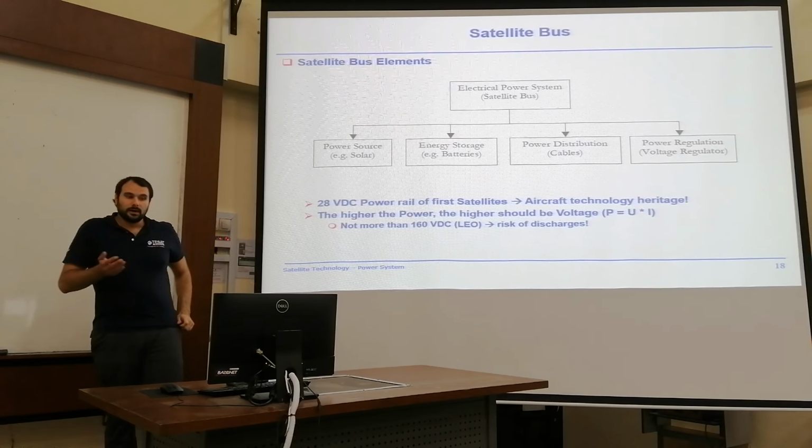We have a very simple system. We have the satellite bus that you can power by either the solar array or the battery. But in terms of the battery, we need to take care if we have a charge and discharge unit, and in case we need to dump some of our power because our battery is full, none of our components want any more power, but the sun is still burning up there. We need to find a way to get rid of the excess power. This is done by the S3R.